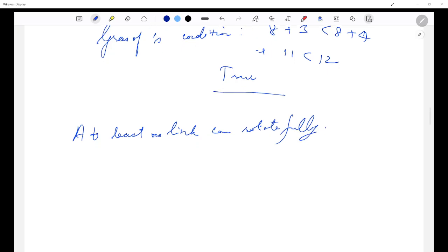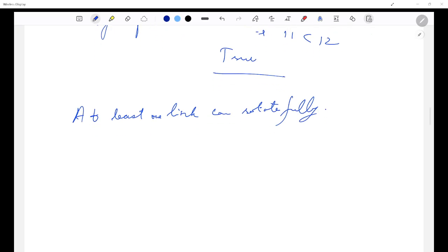Here the shortest link L1, equal to 3, is adjacent to ground, so theta 1 can lie anywhere between 0 and 2 pi. For this 4-bar, for most input angles, there are two assembly configurations, either open or crossed. So for each input angle, there are two coupler curves.